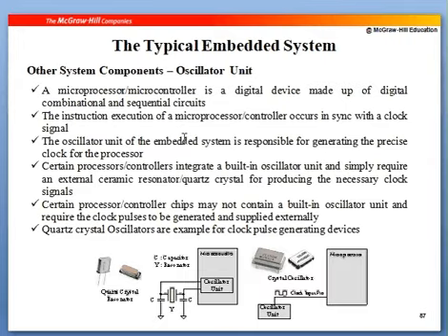So here, for the oscillator frequency, you have two ways for your microcontroller. You can use an oscillator unit with two wires, and you can use a resonator circuit, which you call a crystal resonator circuit. Parallel to this resonator circuit you have two capacitors.